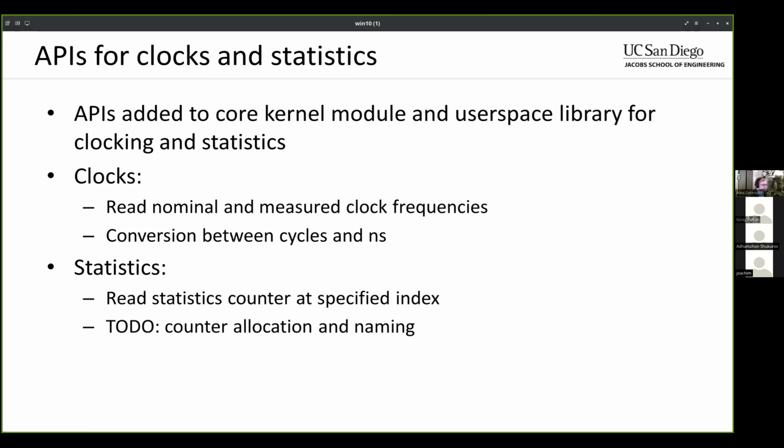But yeah, basically this resulted in the DMA benchmark application module, the extension kernel module, not working correctly because it was looking for the statistics counters in the wrong spot. So with these couple of changes, I've now gone through and overhauled that module such that it's now using the correct APIs and reading the correct locations in the correct registers. And let's see, I think I did, oh, I also did a couple of other things. I guess in the mqnic dump code, it's now reading all of the clock info and dumping that, and it's also reading all of the statistics counters and dumping those.